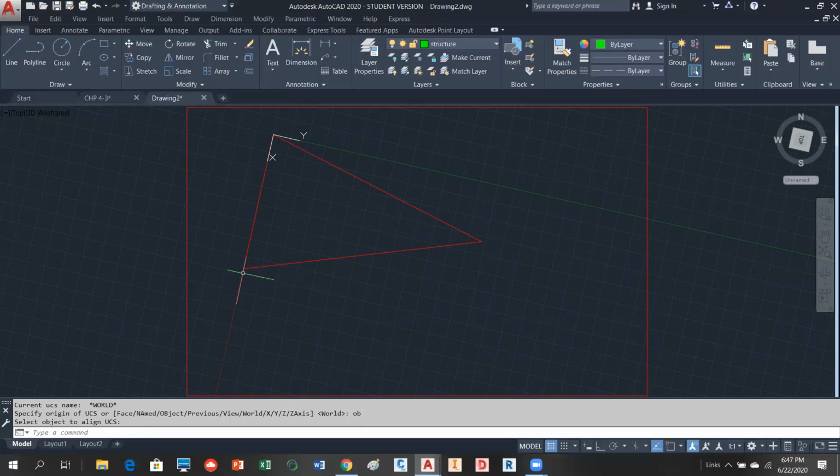So we're going to put in point 50 and 51, okay? So the way you can do this, you can go over here to draw, and there is this guy called multiple points. Multiple points. So to specify this point, since we are working everything off of this origin, we don't need the @ symbol. So we're used to using that @ symbol, but you won't do it in this case.